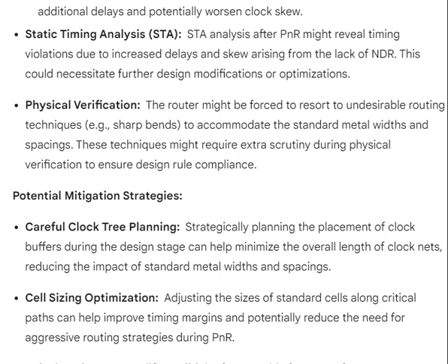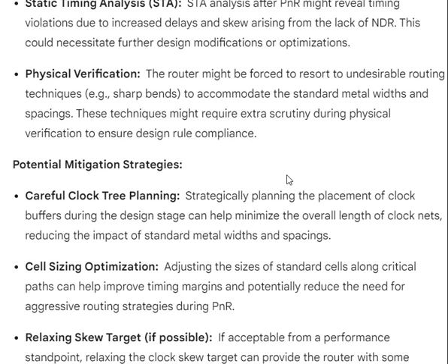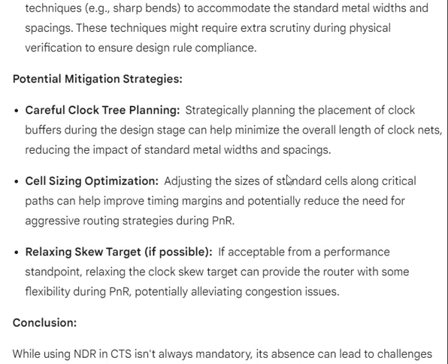Physical verification. The router might be forced to resort to undesirable routing techniques, e.g., sharp bends, to accommodate the standard metal widths and spacings. These techniques might require extra scrutiny during physical verification to ensure design rule compliance.